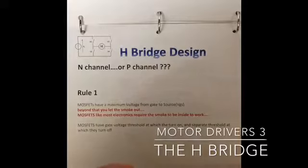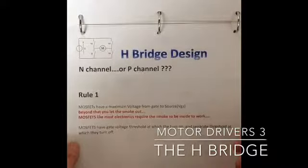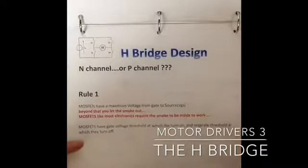So rule number 1. This is one of my rules I've learned by trial and error and a lot of things blowing up. MOSFETs have a maximum gate voltage to source, VGS. Beyond that, you let the smoke out. MOSFETs, like most electronics, require the smoke to be inside to work. MOSFETs have gate voltage thresholds at which they turn on, and a separate voltage at which they turn off.